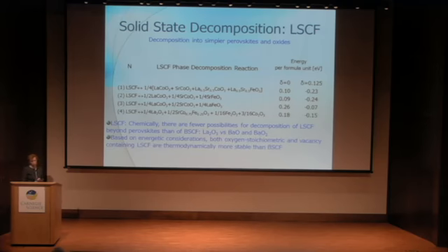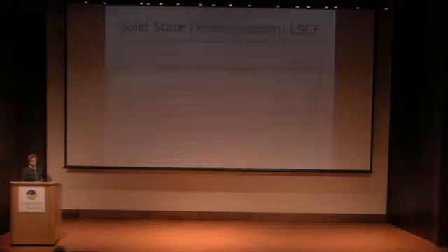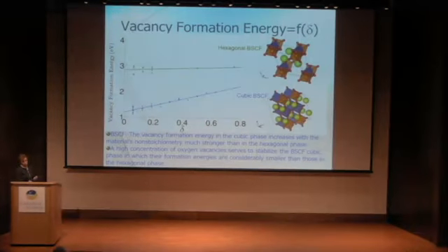And based on energetic considerations, again, both oxygen stoichiometric and vacancy-containing LSCF are thermodynamically more stable than BSCF. Unlike BSCF, LSCF is expected to preserve the material's integrity in devices under a range of conditions. So to say that this is a solution, probably not, but at least LSCF seems to be a little bit better than BSCF in its behavior because it's more stable.